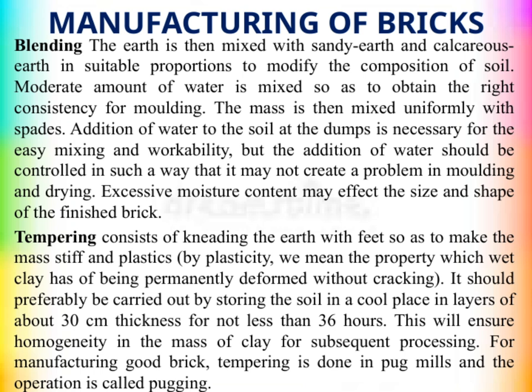In modern manufacturing, tempering is often done in pug mills, and this process is called pugging. It ensures the soil is evenly prepared for the subsequent steps in brick production. So, in summary, blending and tempering are foundational to creating consistent, high-quality bricks that meet the desired standards.